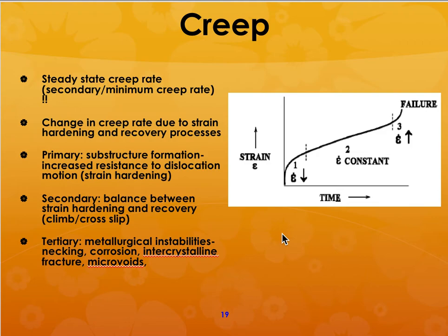So what are some of the important points? In the second stage, the creep rate is called the steady state creep rate. So this alone determines the time you have before the component will fail or rupture.